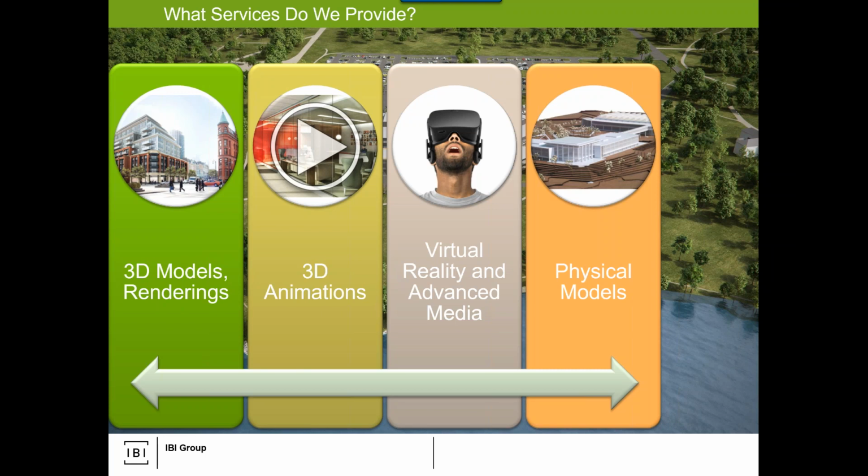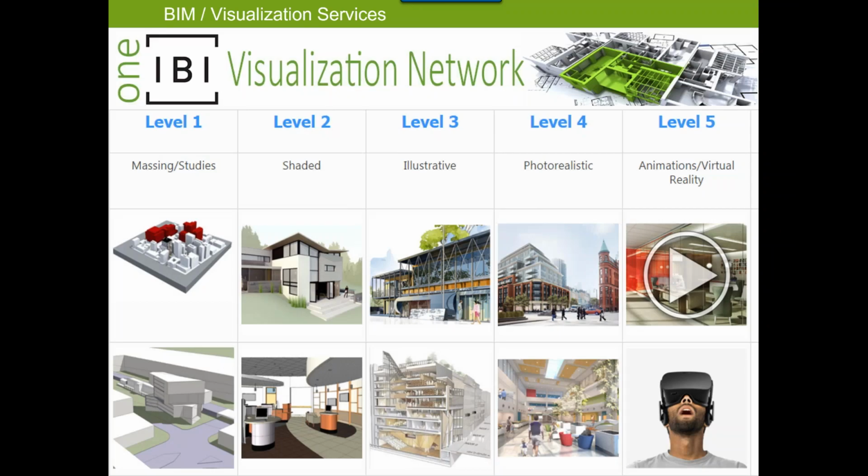Then you have the Viz guys that will want to show absolutely everything, with the finite details of the materiality and the furniture and how things are interacting with each other, so that you can achieve virtual reality, or go into some export format to feed into the physical model machine. The physical print models usually use a format called STL or OBJ. Virtual reality may go FBX into tools like Unity or Unreal gaming engines. And all of that, as a BIM coordinator, you just need to help facilitate the workflows between the professional experts from the design side and the virtual reality side, or the Viz side.